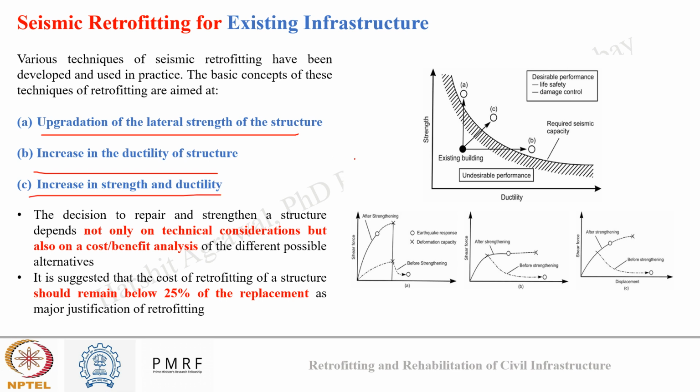As can be seen in the image, when talking about the performance of a structure, there are two aspects, strength and ductility. In terms of seismic activity, my infrastructure should either have high strength to bear the lateral load without much drift, or it should have high ductility to absorb or transmit the seismic waves without collapse.